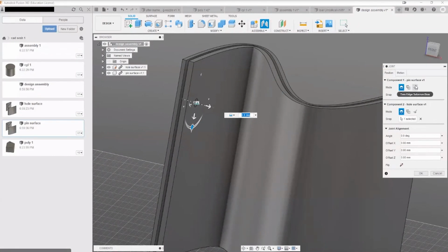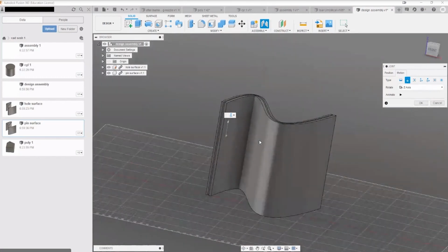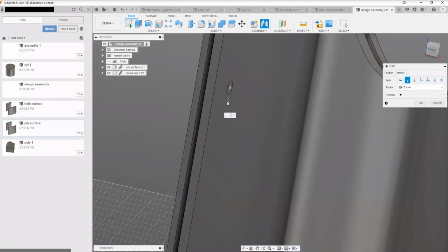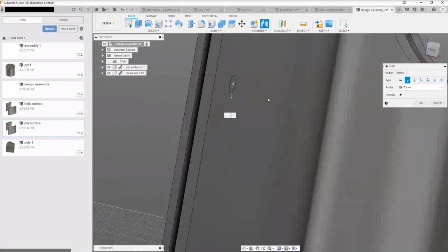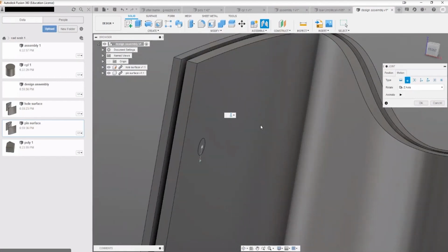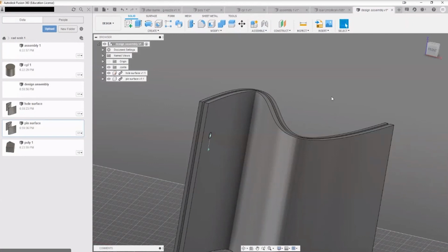There's different motions over here, like revolute. So, for example, if you don't have any constraints in terms of which orientation, because remember a pin is circular, right? So it can rotate. If you don't have anything specified, and you have your collision control off, that's for later, really. Again, it's unconstrained. So technically, this little thing is going to keep rotating all the way through, and you want to avoid that. So even if this is a revolute component, there's another set of constraints that you can do.